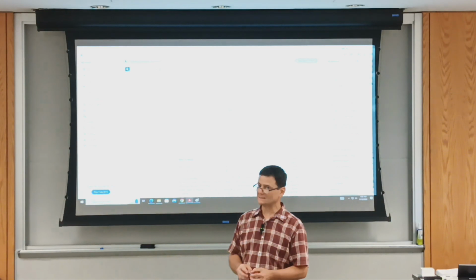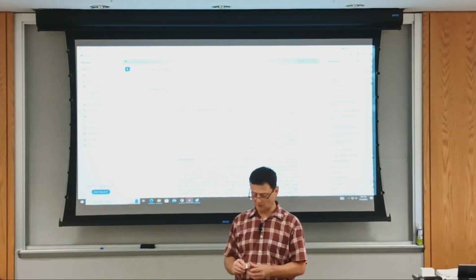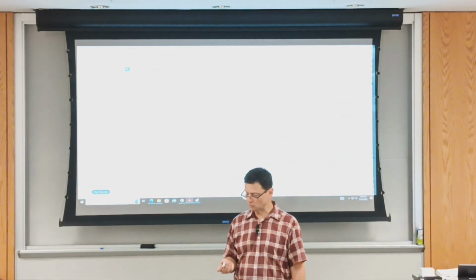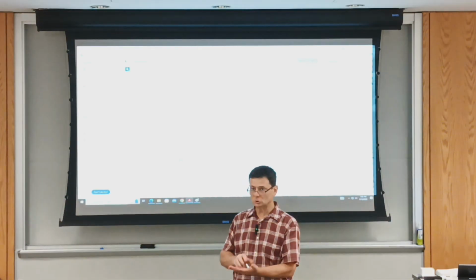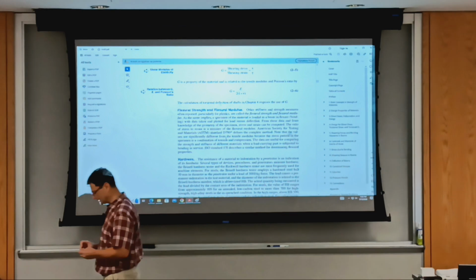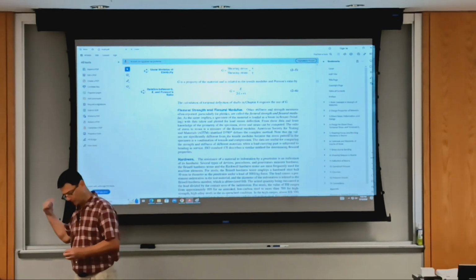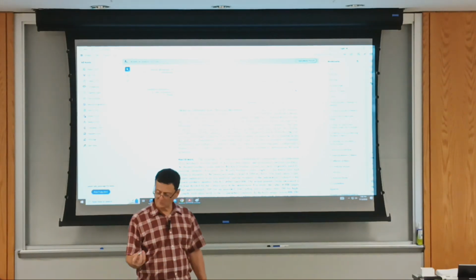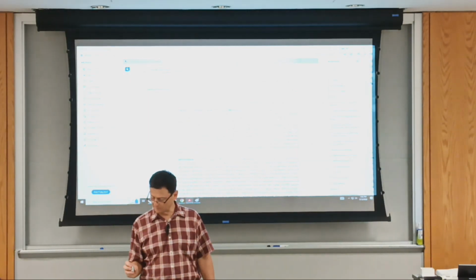The hardness test is a non-destructive one, and probably the easiest that you can do. All you need is just two parallel surfaces and the respective equipment. We have Vickers hardness equipment in 118, where the tensile equipment is. I have here a specimen, a modified crankshaft that a Capstone company in town made for us, and you can see the places where they did hardness tests.